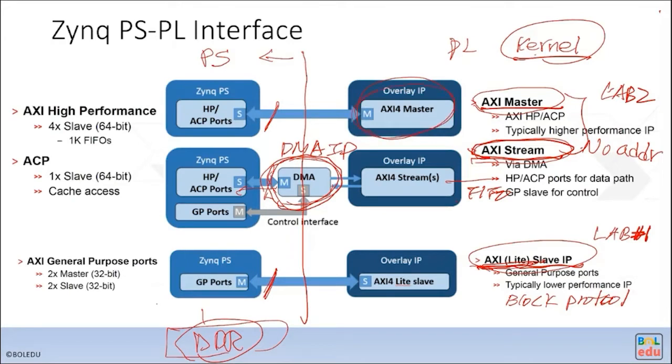For the AXI master, the bus protocol has the address information. However, its address is also specified through the AXI Lite. You need to use a CPU to program the address for the AXI master access. So AXI Lite is a very important interface.